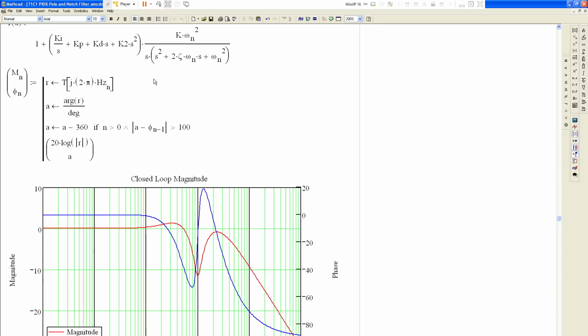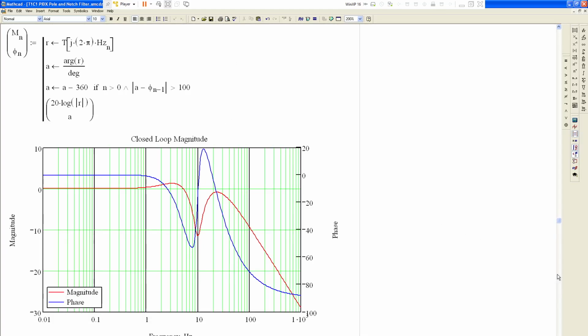So the point is that eventually what you end up looking at is that the closed loop transfer function is just a polynomial with a numerator and a denominator, and it could have any number of terms. And it requires a little bit more mathematics if you're going to have something to the third power, like this is, well, this is actually a fourth order system here. And so the mathematics gets to be a little bit more difficult. I didn't want to show this or do the math, but I did want to show the effect of what the zeros can have, and they can be an unknown gotcha if you're using the wrong values of P, I, and D, even if you are placing the closed loop poles where you want them. So that's the point that I want to make.